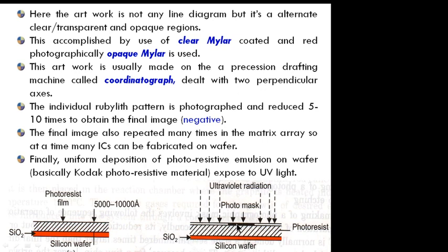So the dark mask region of the photoresistive material is still in a gel shape, an unsolidified region, which you can remove. Then you can reach the SiO2 or silicon oxide layer, and when you touch that one, naturally you can further do the process on the wafer itself.